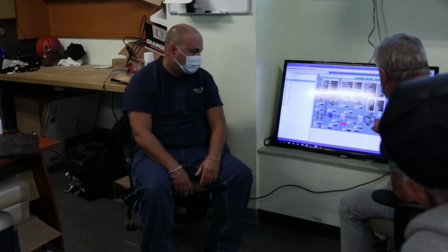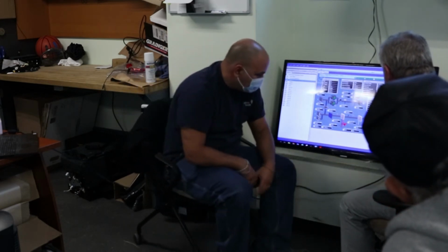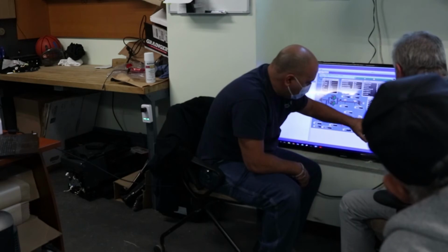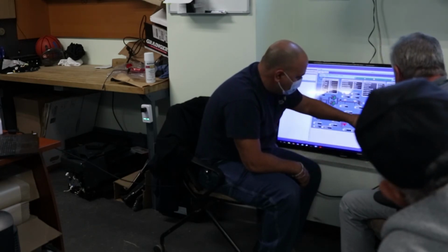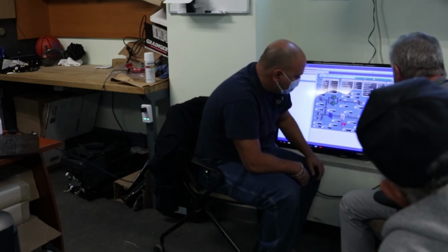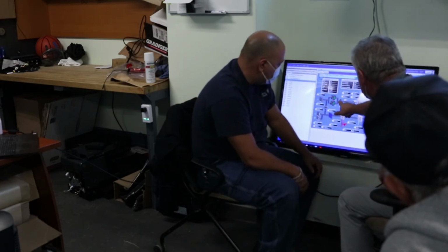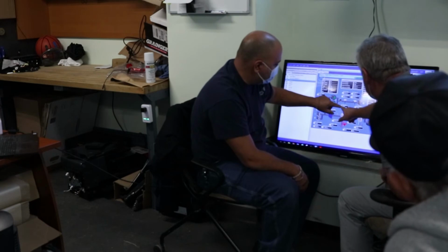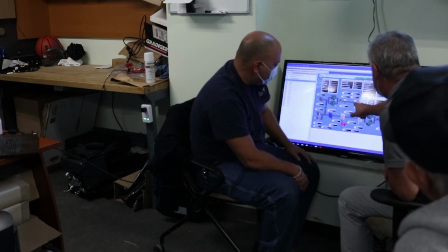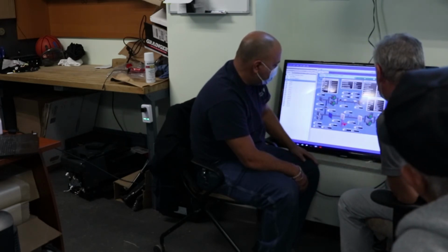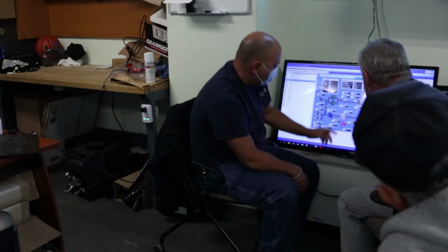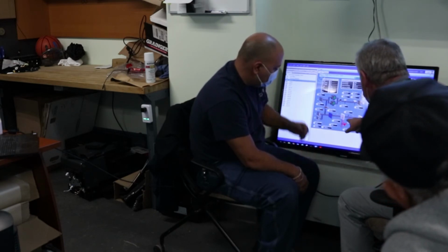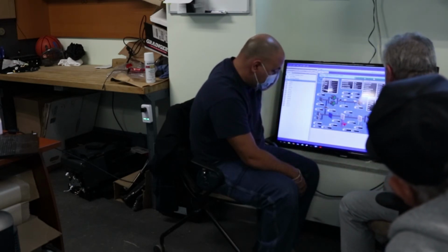Another simple question: what is this? This is the high pressure safety. This is the temperature sensor above it. This is the low pressure sensor. What is this? That's the CO2. This is the preheat, and this is the freeze stat. This is also the mixed air temp.